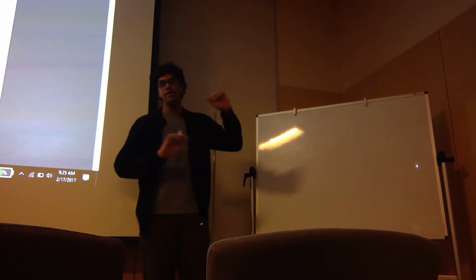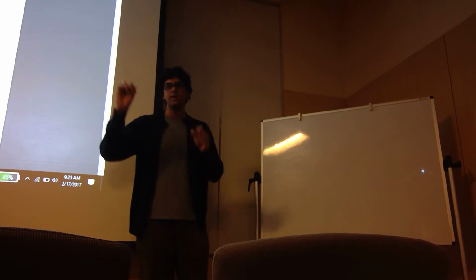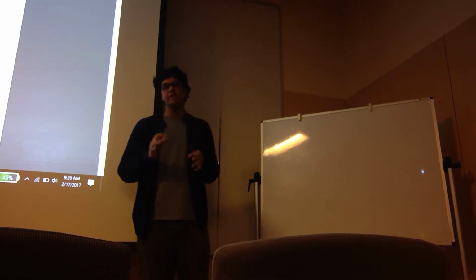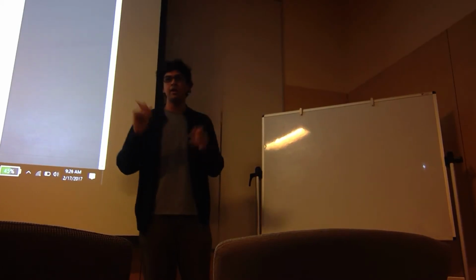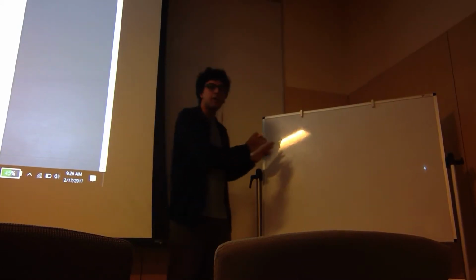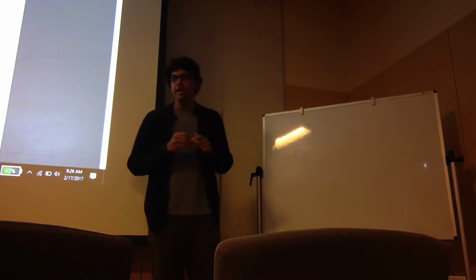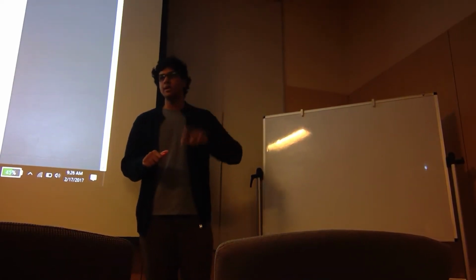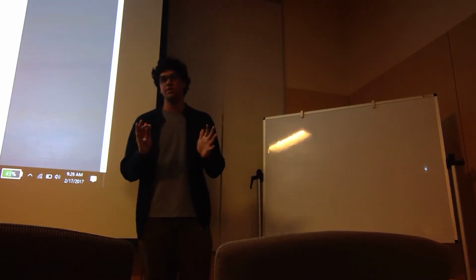Process designers have already simulated and tested it out and come up with certain rules. The only restraint they put on a circuit designer is that they follow these rules when making the layout, so that when they actually do the process, all these problems will not occur. So it's very important when you make a layout that you understand the design rules specified by your foundry, and follow those rules as much as possible.